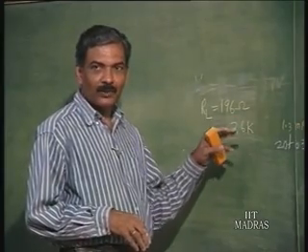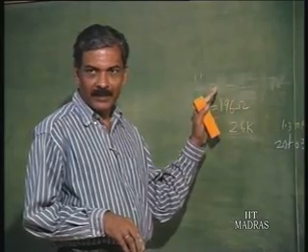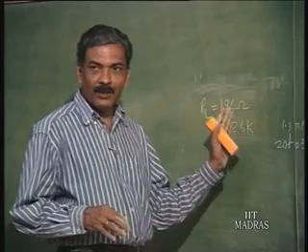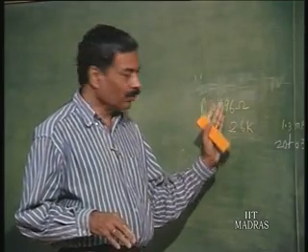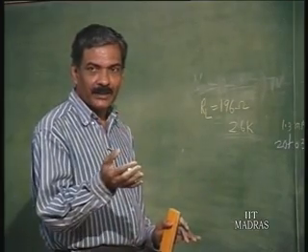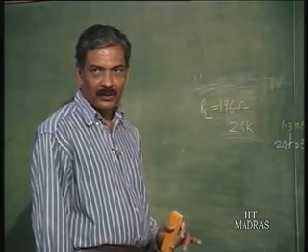And you can also plot load regulation by varying only this kind of resistance, because load regulation becomes meaningless beyond this range. Vary the load from 196 ohms to 2.6 K and find out how output voltage varies with respect to this variation of load.